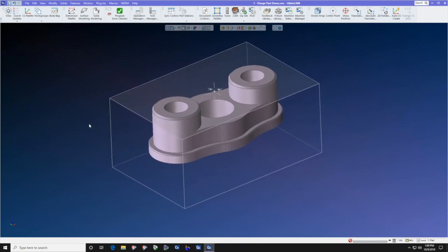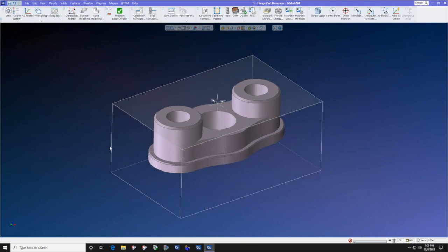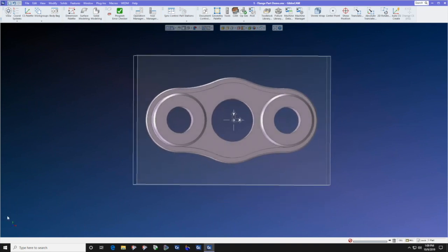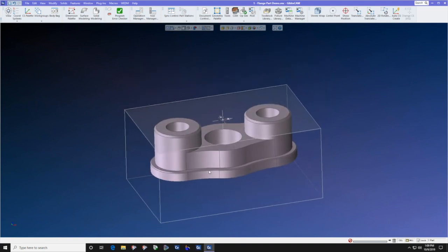Now, preparing the part for machining. We aligned this part to the coordinate systems of the machine, and as you can see, it's perfectly aligned with the X and Y axis. If it wasn't, if it were turned or skewed, we could extract geometry, find out what the angle is, and skew it back using 2D rotate. But I want to talk to you about something else that people don't know about solid models. When you import a solid model, and I get this question a lot,